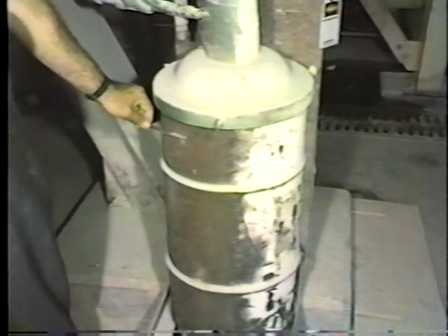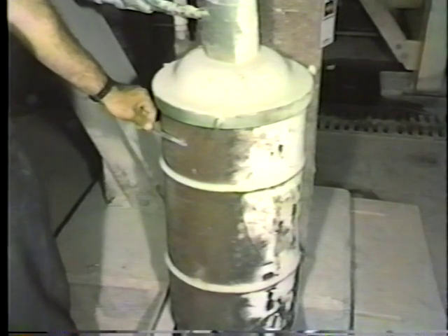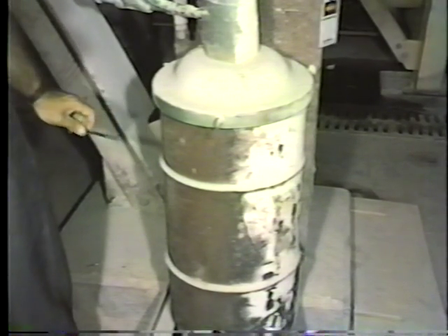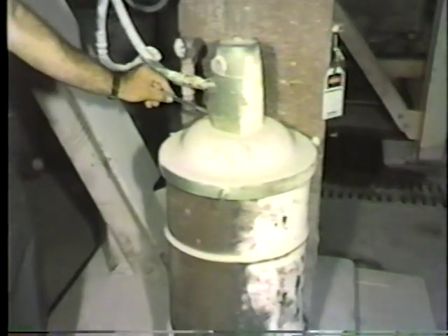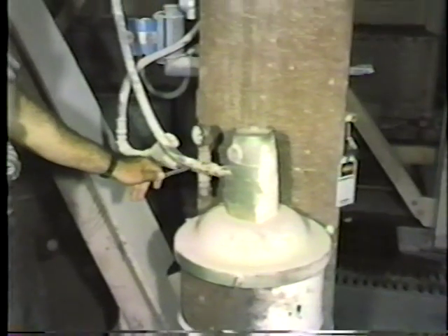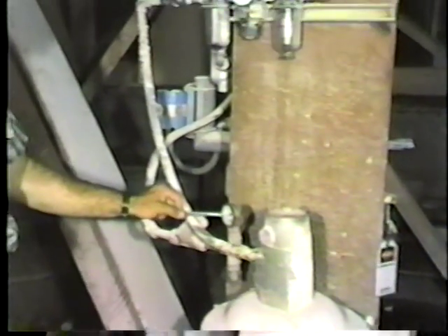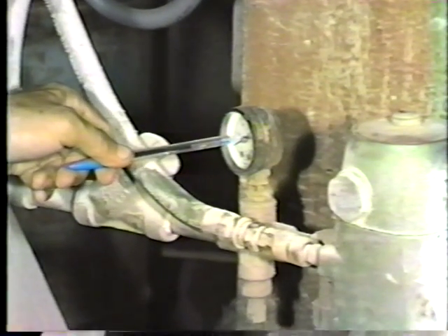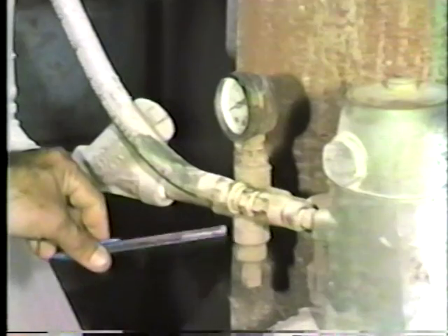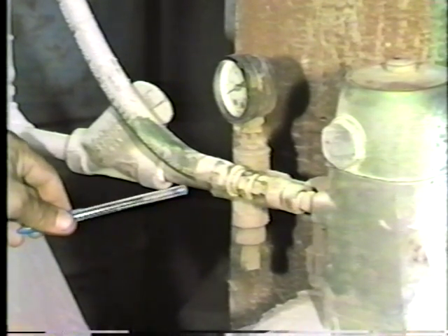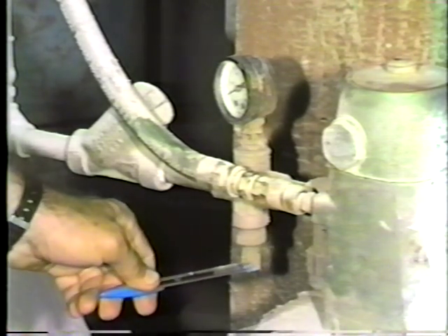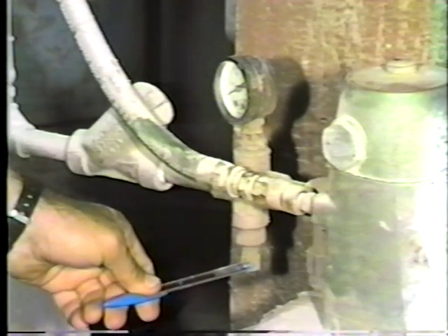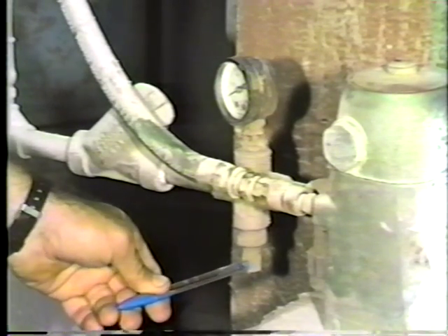This has a lubricant, Mobiltemp 78. That's a high temperature lithium-based grease. All right. Now that pumps the grease from there where? It comes out through this fitting to there's a high pressure indicator which we're operating at about 1,000 to 1,500 pounds per square inch. If we get an overpressure in the line, a blockage, rather than rupture a line downstream, we have a rupture disc here that is set to relieve the pressure at about 2,000 psi.